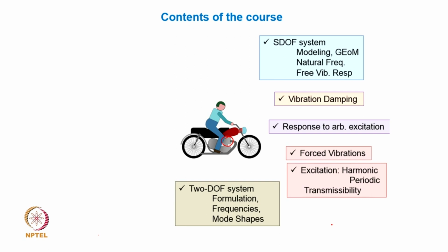we discussed that this automobile, as we see a vehicle with the rider, we model like a simple mass with a spring and a dashpot in parallel as an initial level model, but we also discussed that the same system can be modeled by a system wherein the front and the rear axle suspensions are independently modeled as two separate entities. And in addition, because we might also be interested in investigating the pitch motion, which quite often gets excited because of a variety of reasons.